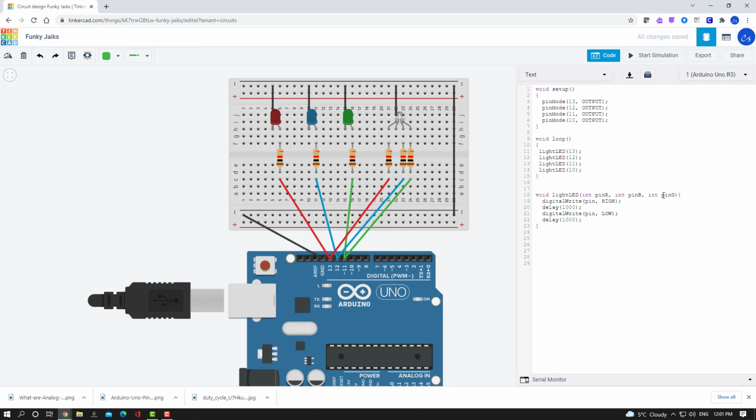So the problem with doing it this way is we can't actually toggle the high and low off. They're just going to all go on or off depending on which numbers we call. And while that might be acceptable, we may get an error in the future where the function says, hey, that doesn't work because I'm expecting 3 pins and you're only giving me 2. So rather than going with the pin approach, like we did in the last example, we could go with the Boolean approach of high and low, what we refer to as on and off.